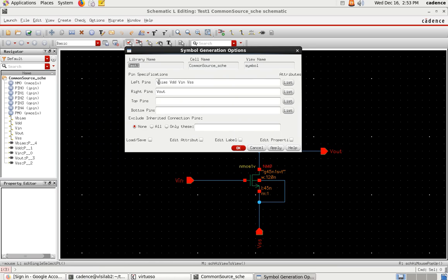So how you want your pins: on the left or top or the right or the bottom, right? For my convenience, for the future circuits, for amplifiers, differential amplifiers and operational amplifiers, because the same module will be used in the future experiments, I'll keep the Vbias pin on the bottom as well as the VSS pin on the bottom, whereas VDD on top and Vin on the left.